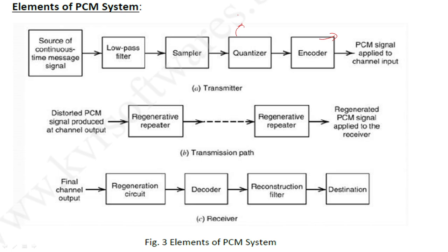For example, here this image is converted into an analog signal, and this analog signal is passed through a low pass filter. In the low pass filter we get only the required low frequency, and this analog signal is again converted into samples. Sampling rate is there, so it should compulsorily be converted into the required sampling rate. Then only we can reconstruct easily while decoding the signal.